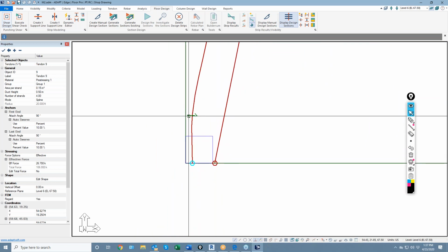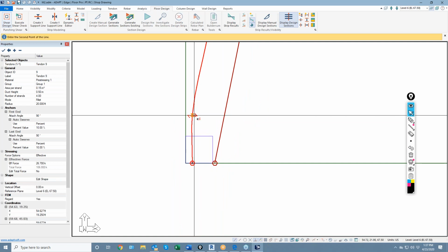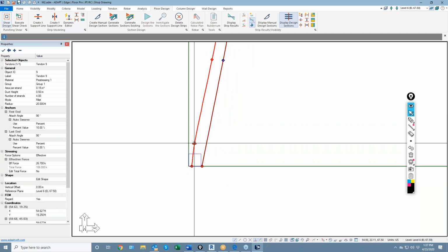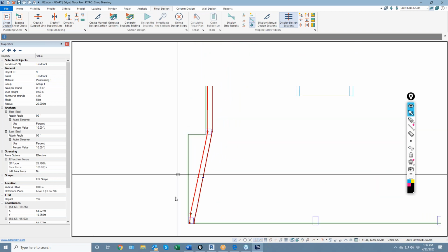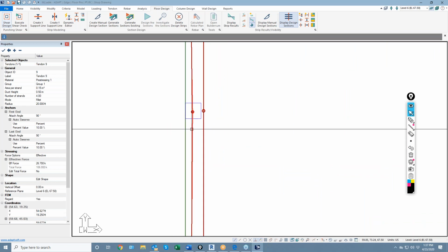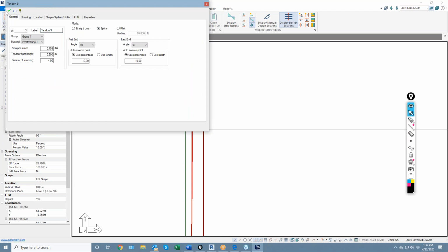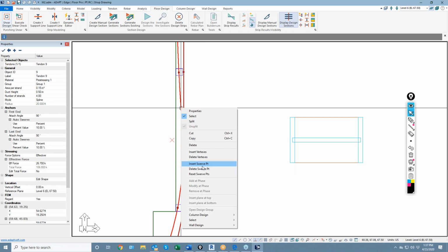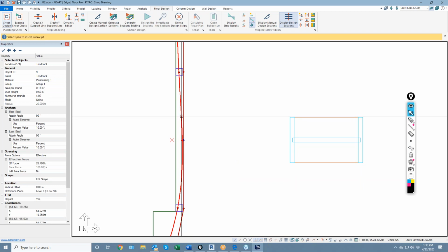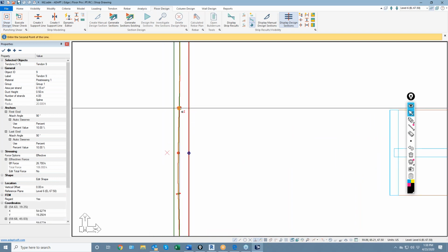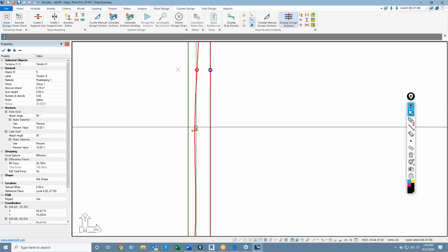There's also a swerve point. So if you wanted to move that cable and swerve it here, then you could adjust the curvature of the cable by using these swerve points. And you could always add a swerve point to a span. So if I was to take this back to spline and say, well, I don't want that to kick out this direction, I could just right click, or I could go to the tendon tab, and we could insert a swerve point, maybe like so, to straighten that out. And then I can control the in-plane sweep of the cable just using those points.